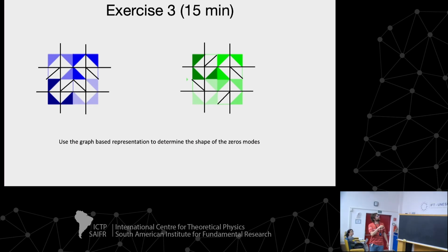For the lattice exercise we had yesterday, you can analyze the floppy modes by looking at the null space of your compatibility matrix, but it doesn't really give you a nice mode decomposition. If you do the metadoku, or the Sudoku metamaterial, you add your directed graph on top, and the arrows give you a nice decomposition of the modes in principle.